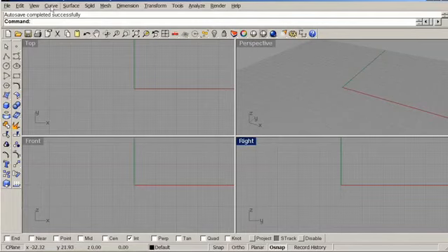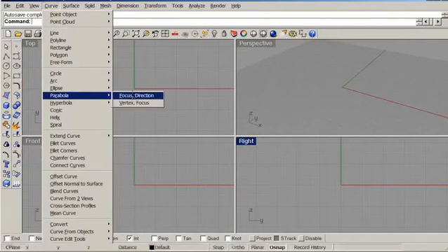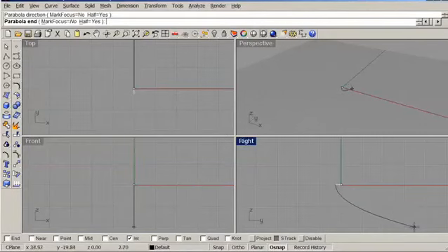And in particular, what I'll do now is design a faceted reflector like I might use for an illumination application, export it, and then bring it over into ASAP. So let's start with a parabola, and let's start with putting my focus position and my direction, and then let's draw the parabola. Because I'm going to revolve this surface, I'm only going to draw half of the parabola.